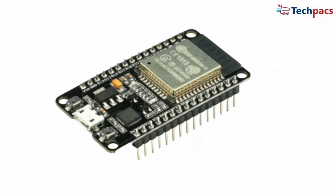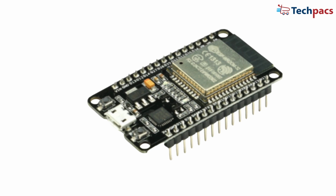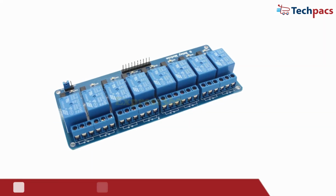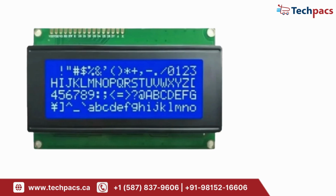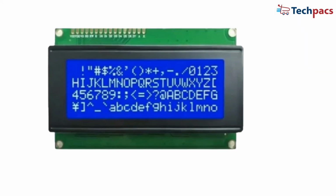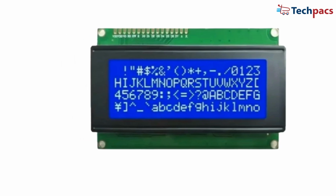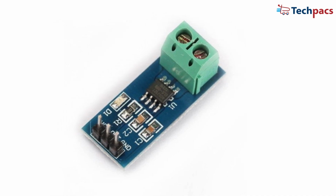ESP32 microcontroller. The brain of our system, handling all the data processing and communication. Relays. These relays are divided among 3 rooms, controlling different electrical loads such as sockets and bulbs. 20x4 I2C LCD displays the current status of each room and the total load, providing real-time updates. Current sensor measures the current load to ensure it stays within safe limits.